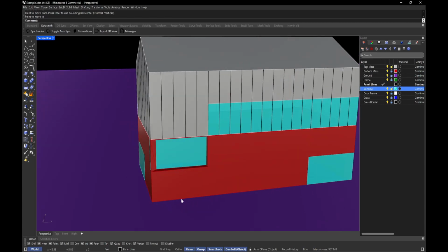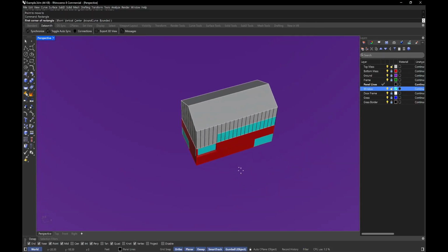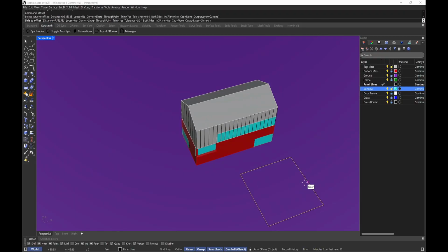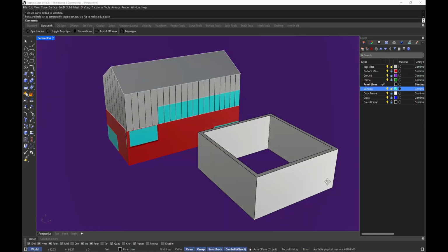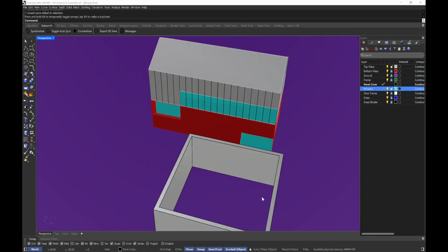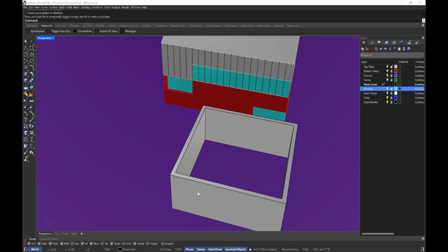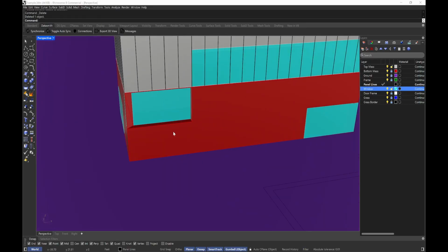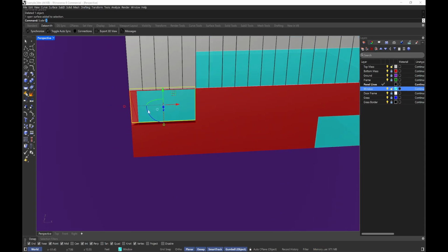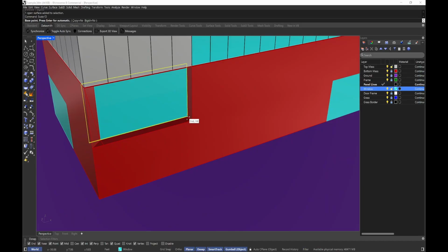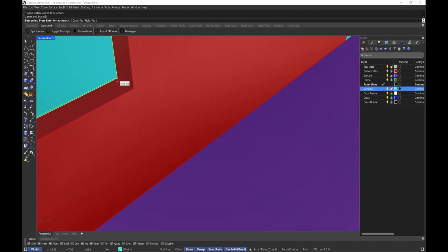If you don't want that to happen, you could draw 2 rectangular curves at 2 feet. Let me just show it to you real fast so you understand. To avoid this, you can do a rectangle like this, right? And then offset that rectangle 2 feet, right? And you can take these two together and extrude it up like that, and see it'll give you a thickness like that if you wanted to. And then you can go in and you can subtract from there. But I honestly actually don't mind this angling here. This actually looks pretty cool, so I'm just going to keep it. So I'm going to scale 1D. Make sure. Yeah.